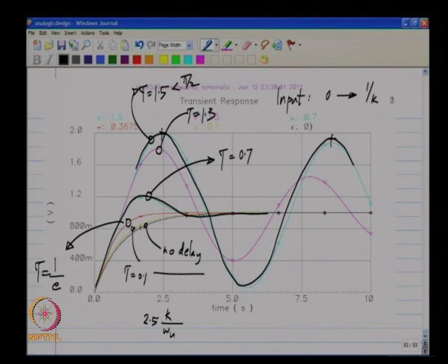So, you do not want any of these things, you would not want to use this much delay. So, this is about the maximum that you can tolerate, or in practice maybe even smaller, about tau equals 0.5 or so. Okay. For that, there will be just a little bit of ringing and not much overshoot, and the response dies out in a reasonable time, and you will get the steady state solution in a reasonable time. Okay.